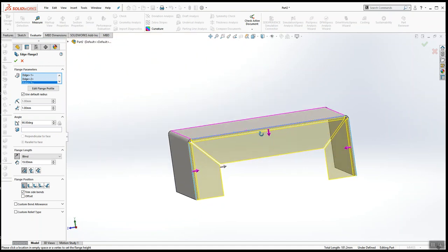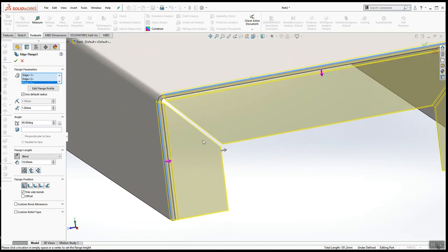And you'll notice what SolidWorks is doing is it's adding a gap, and it's adding reliefs in the corners so it doesn't tear. My gap thickness, I'm going to change to 0.5 millimeters. And everything else can be left as default, except the length is going to be 40.